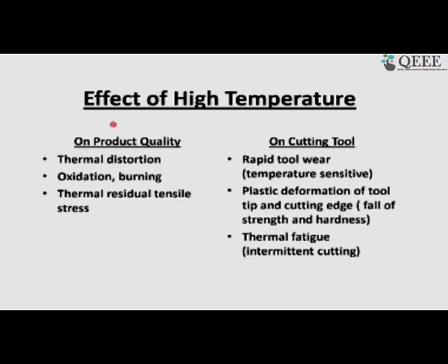And then we go to the effect of temperature, why we should deal with this at all. So, friend, two things just now I have mentioned, it is force and temperature, it is on the product quality and on the performance of the tool. Both will be affected. So, we have to pay attention. Now, how this quality of this job is going to be affected? You know, if you do not have uniform temperature, there may be thermal distortion of the job. Then you have oxidation on the job. If it is in open atmosphere, temperature is quite high, it is a virgin surface, it will be immediately attacked.